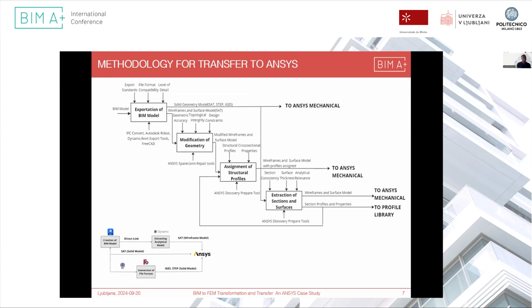So the exportation of the model as lines and surfaces includes extraction of the analytical model using Dynamo in Revit. And then after extracting the lines and surfaces, the model was exported using the SAT format to ANSYS.